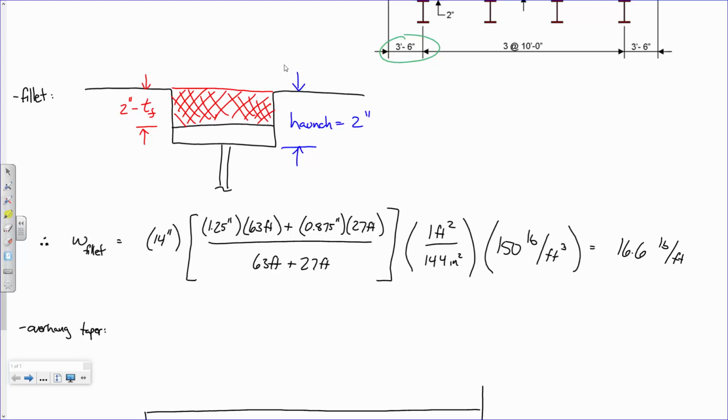The reason I wouldn't do that is because, first, there's nothing preventing that, but I think it creates a little bit more of a complication from the fabrication side. But second, you do actually get a little bit of a capacity benefit from having that extended out a little bit. Moment equals force times distance. So separating that out, you do actually get a little bit of a bump in capacity. I'm curious how their formwork was set up, though, to have that just embedded. A little interesting. It's uneven. In the beginning, it's outside the deck, and then it goes inside.